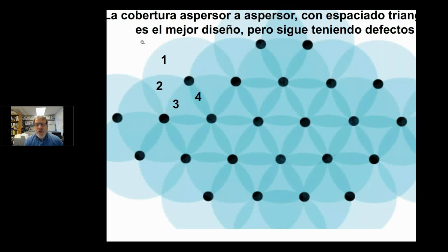This just elaborates on that example a little bit, showing you that only 1 irrigation head impacts here, 2 irrigation heads impact this area, 3 impact this area, and 4 heads impact this area here. Yeah, so it'd be 4 and 3, 4 and 3. So that is not bad. When there's 6 heads impacting an area, the distribution is okay, but it's still the difference between 4 impacting this area and 3 heads impacting this area.